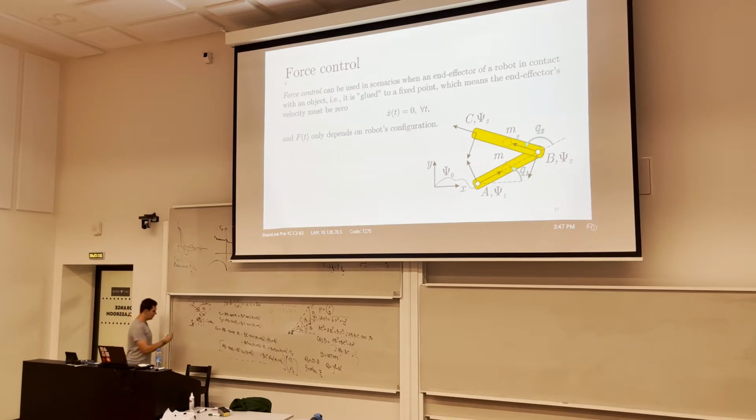If we multiply force with velocity, what will we get? Power. In order to tackle this force, we need to produce the same power by means of our motors. So here we can apply torque, tau 1, tau 2, and those components are supposed to be equal.